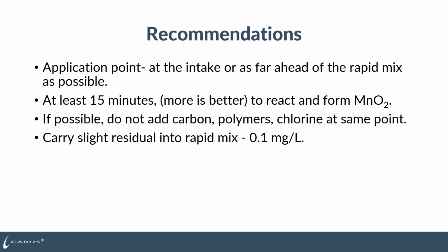Lastly, with chlorine, in the case of organics, if they react with chlorine to form THMs and HAAs, that's a one-way path. Once you form the THM and HAA, it's no longer reactive with permanganate or any of the other preoxidants. So if you're feeding chlorine dioxide or ozone, once you form a THM or HAA, you can't oxidize it, it's there. So the idea here is to move the chlorine away from your preoxidation because you don't want it forming THMs and HAAs that you can't remove at that point. Move it to the back of the plant so that you don't have it causing an issue for you.